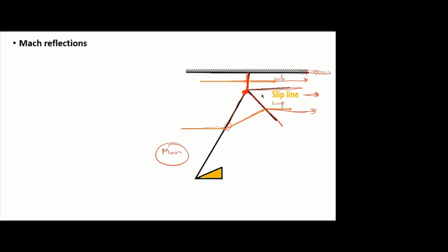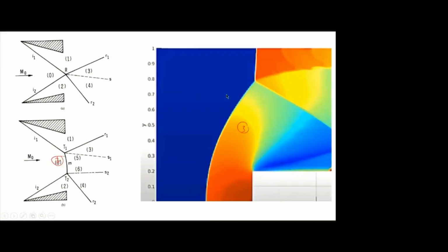This they observed in the experiments. So this is one example, and this is another example. For example, we know in supersonic flow, if you place a bluff body, this will create a bow shock, right? Okay, if there is no wall, what will happen? This bow shock will extend up to a certain distance, then it will vanish. That is normal shock wave, oblique shock wave, then it will become the Mach wave, then it will vanish. This is how the bow shock will happen. But here, special case, here we have the wall.